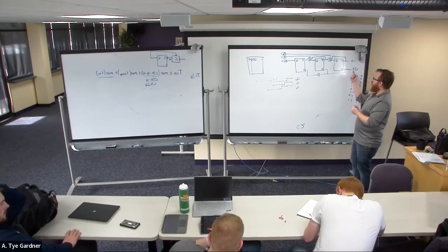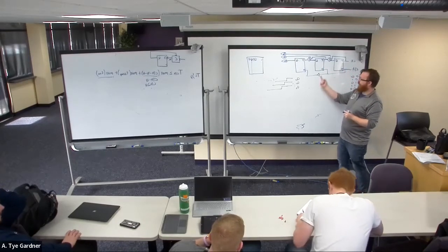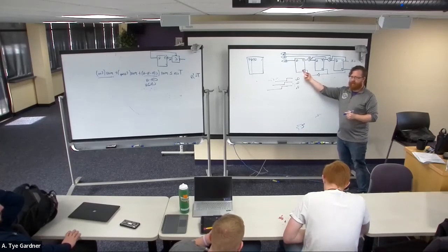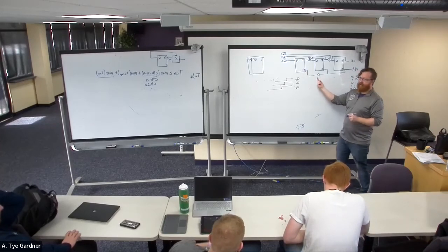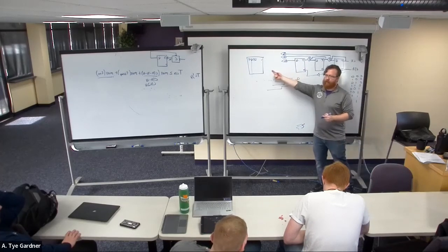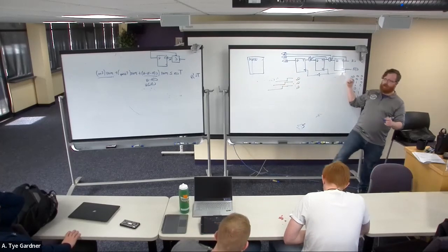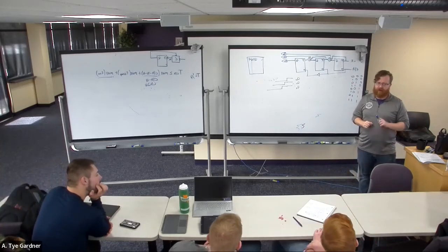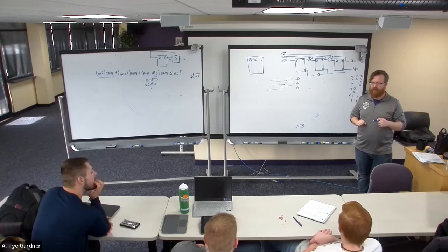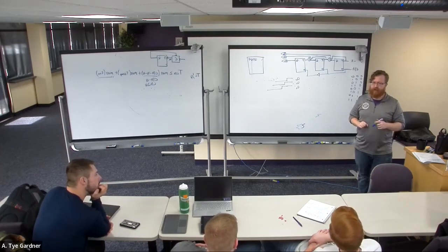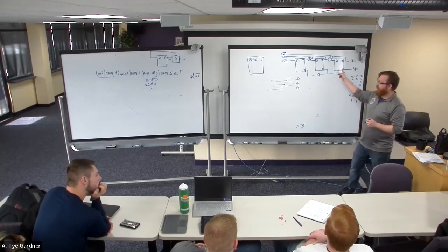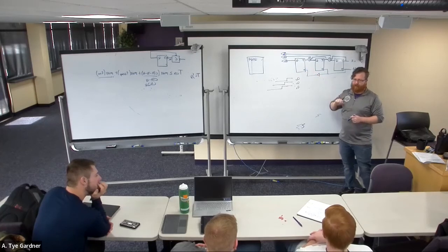Because now this clock is driving 1, 2 flip-flops and 1 buffer. But this buffer is driving this one. So I haven't added or subtracted anything here, but if I add 4 more flip-flops, it doesn't add to the load of the first one. So buffers do have their place. And in fact, clock management, when you start getting sophisticated designs, which we'll hopefully talk about in digital systems 3610, clock management becomes a big issue to make sure that these types of delays don't add up to problems.